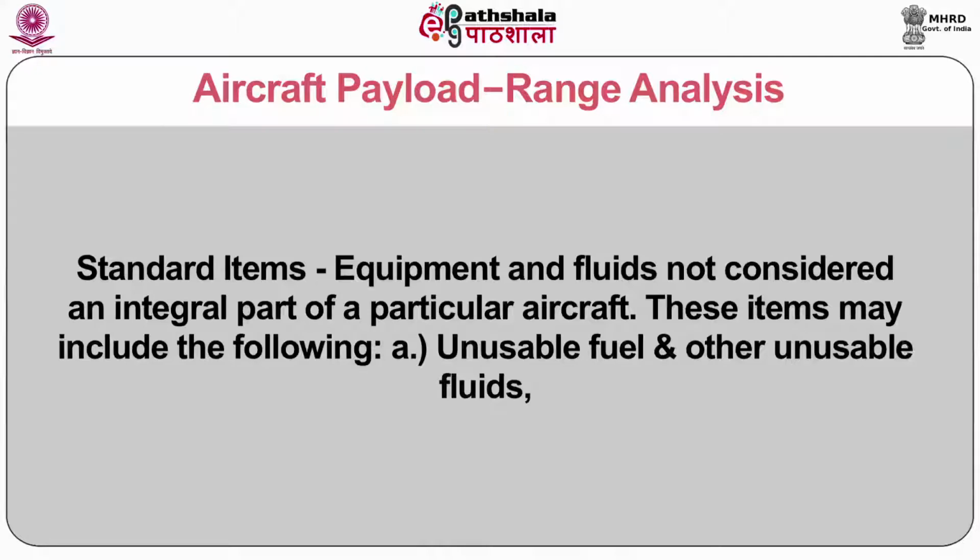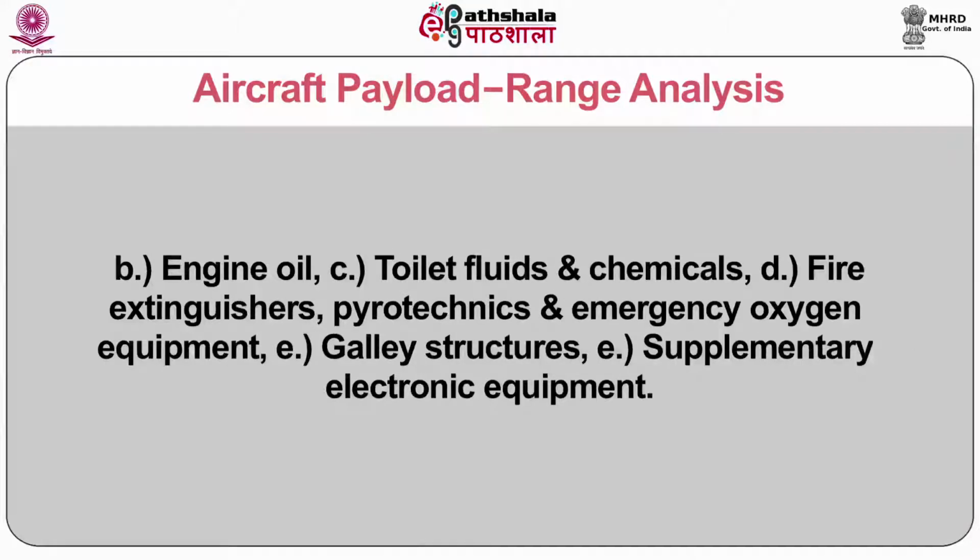Standard items are equipment and fluids not considered an integral part of a particular aircraft. These items may include the following: A. Unusable fuel and other unusable fluids. B. Engine oil. C. Toilet fluids and chemicals. D. Fire extinguishers, pyrotechnics and emergency oxygen equipment. E. Galley structures and supplementary electronic equipment.